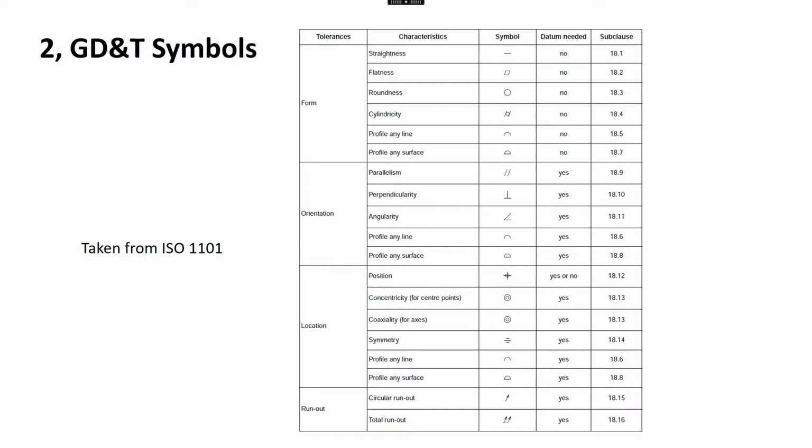You can just say position, diameter 3 or whatever, without having datums in there. Now in the later versions they recommend that you use at least one datum, and I think the reason is you need to make sure that when you're going to drill a hole in something, you've got to clock the right face up first, and it really wants to be that face that you're drilling into. So you clock that face up so it's square to the machine before you drill them holes.